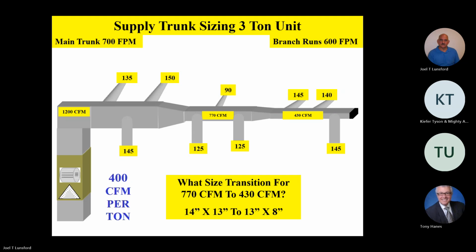Maintain pressure, velocity. Oh, I love that answer. Give yourself a star. That is correct. It maintains pressure in the duct system, because if I was to take that last takeoff and just take it off the very, very end, it would actually depressurize the whole system.